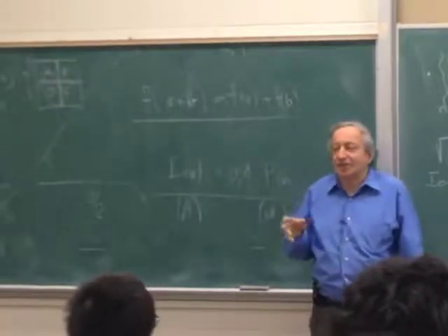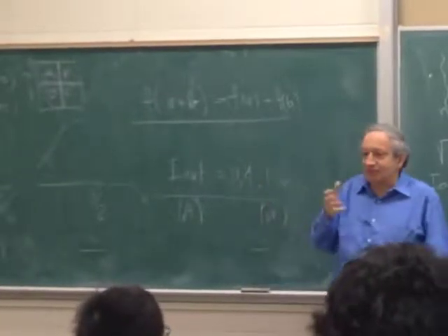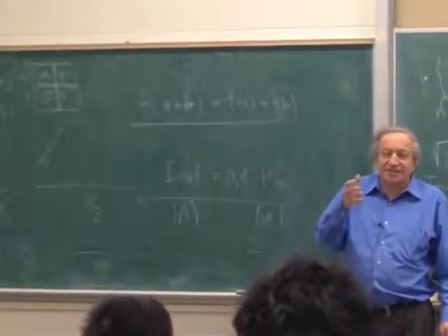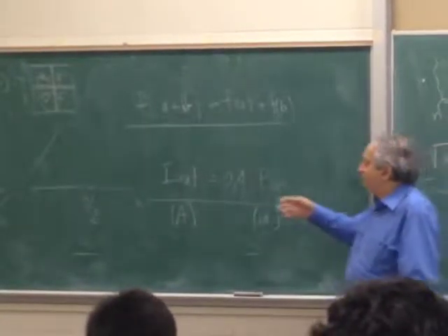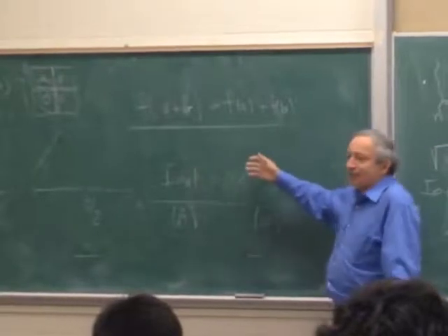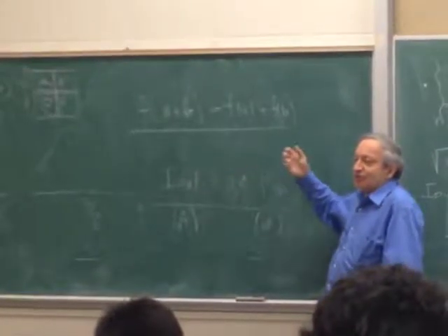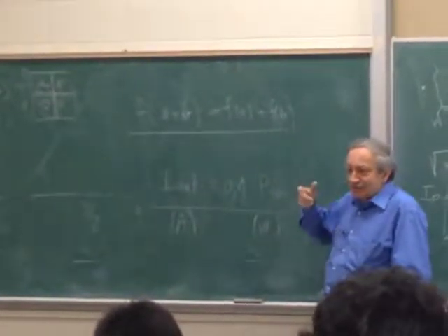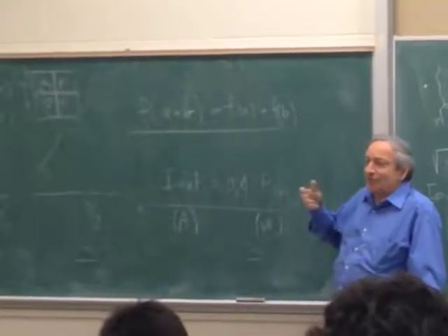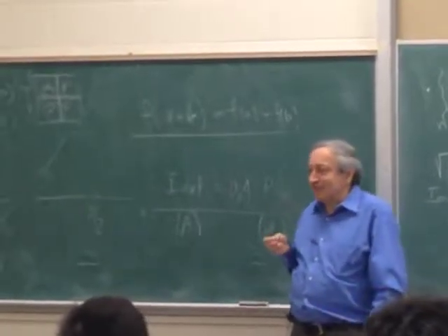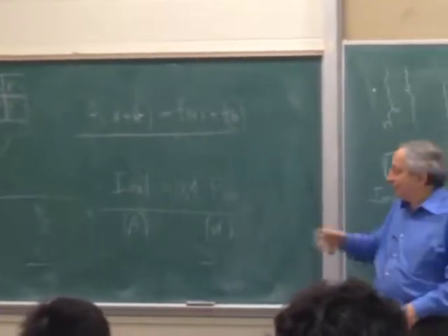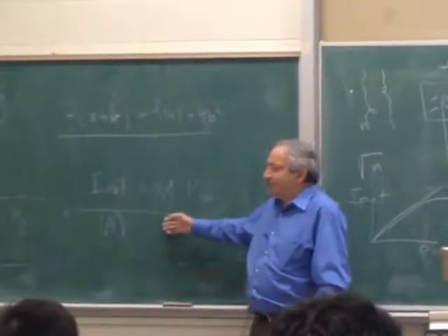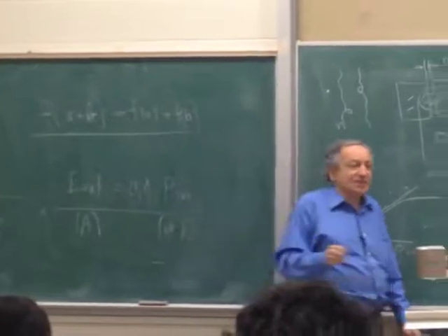But we got the same result by energy consideration, because we said since the efficiency is maybe 20%, if we shine a watt, we should get 0.2 watt. Since the voltage is less than a volt, to get 0.2 watt we need about 0.4 amps. So either way you look at it, as energy from common sense, or by the rule of thumb, this is the basis of designing the sensors.